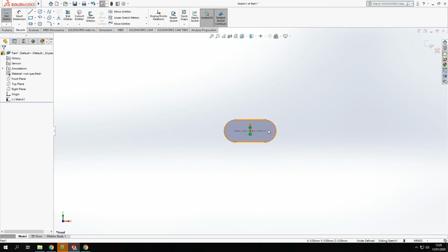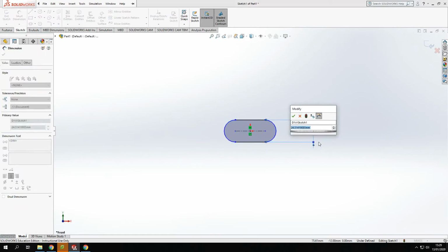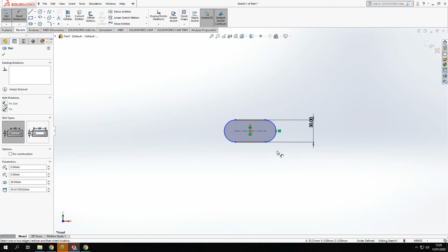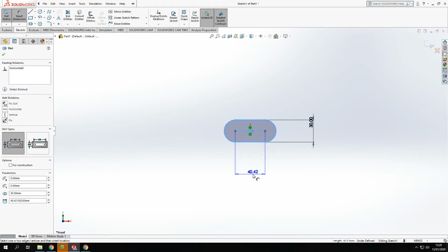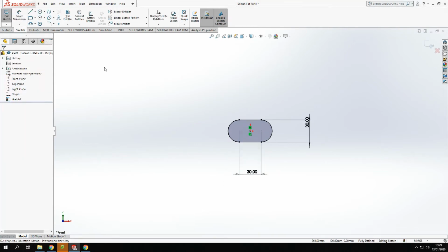Okay, so we're just creating a surface, and that's going to give us some sort of scale. So I'm going to go 30, and I'll set a distance with the center of 30 or so. Now I'm going to sweep this along just to create a pattern.